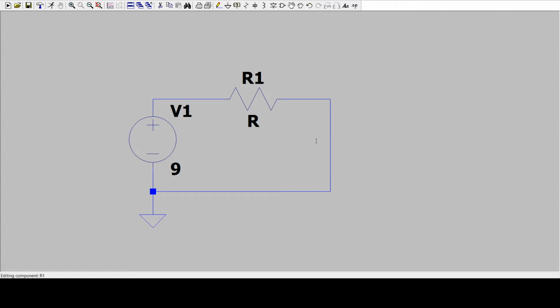So here, if I wanted to say 1000 ohms, which is a kilo ohm, I could specify 1000, or a neat little shortcut here is putting K gives us 1000 ohms as well. If I wanted 1 million ohms, or 1 times 10 to the 6, I can type capital MEG, and that will give us 1 mega ohm. If I wanted a milliohm, which you don't do very often, but occasionally it comes up, you can do a lowercase m, and that will give you a milliohm. So let's stick with the kilo ohm here. So we have 9 volts, and again, you right click here. The series resistance, we'll introduce that here in a later video, but for now, don't worry about it. We have 9 volts here and 1 kilo ohm here.